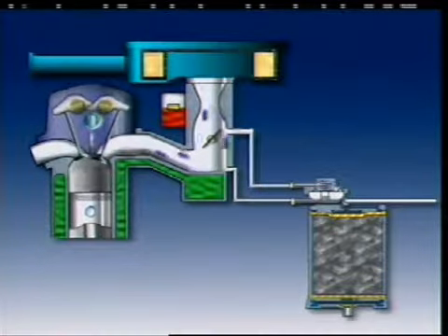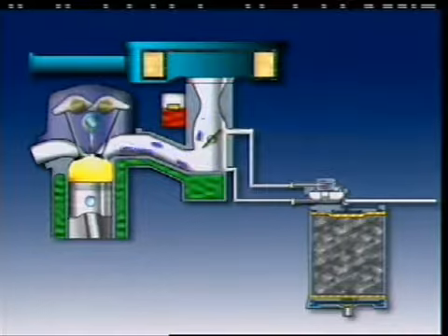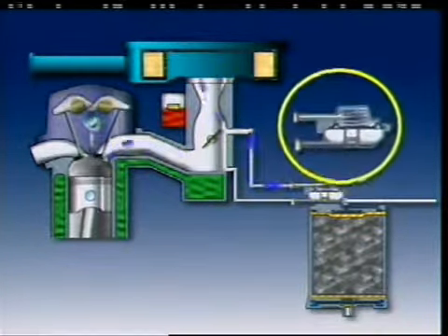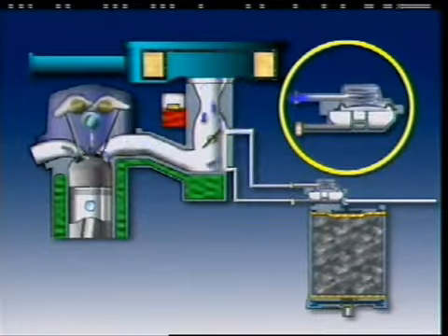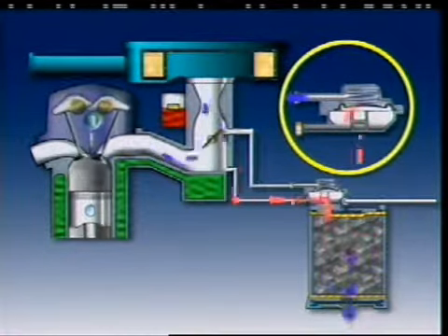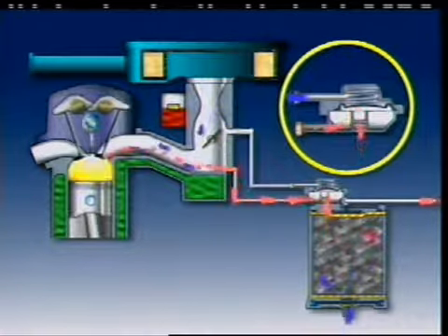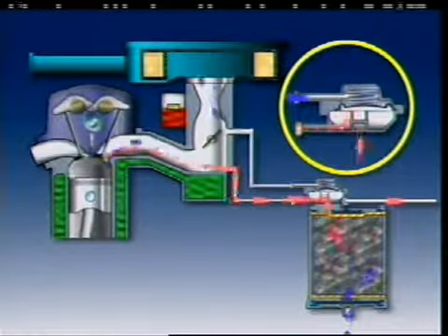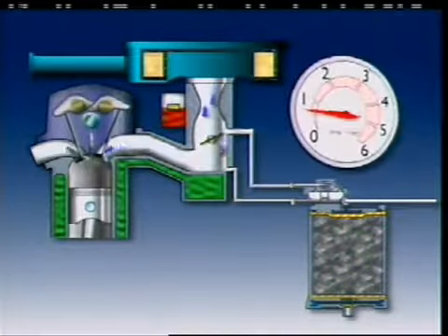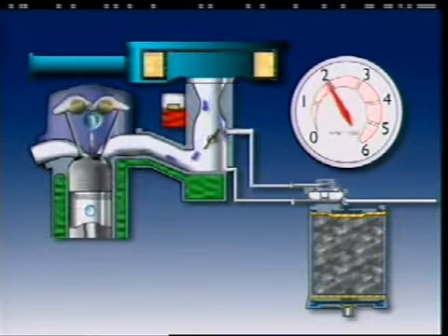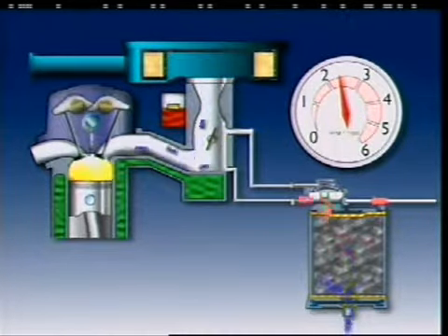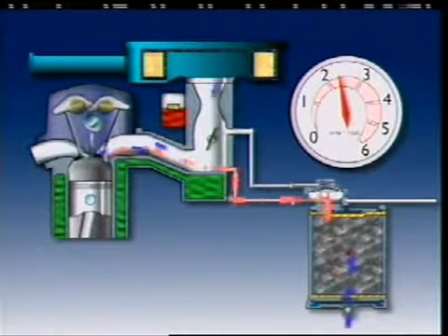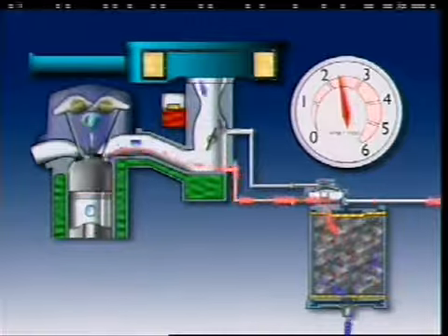When the engine is running, the action of the piston during the intake strokes creates a low pressure area in the inlet manifold. This can be used to open a purge valve, which draws fresh air into the bottom of the canister. The air collects the vapour and directs it to the inlet manifold, where it is drawn into the engine and burned. The purge valve is designed to operate only at speeds well above idle. If it operated at low speeds, the extra fuel vapours could upset the air-fuel mixture, which could cause poor idling and rough running.